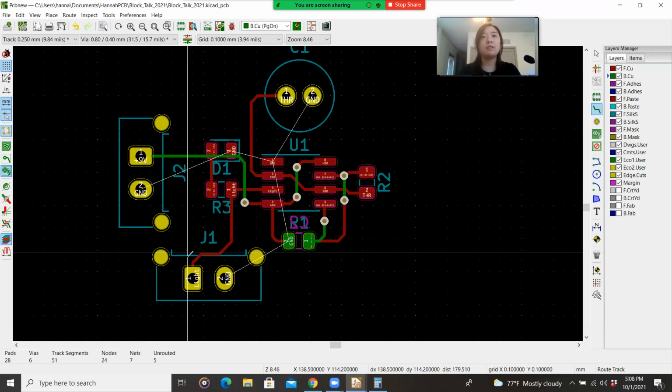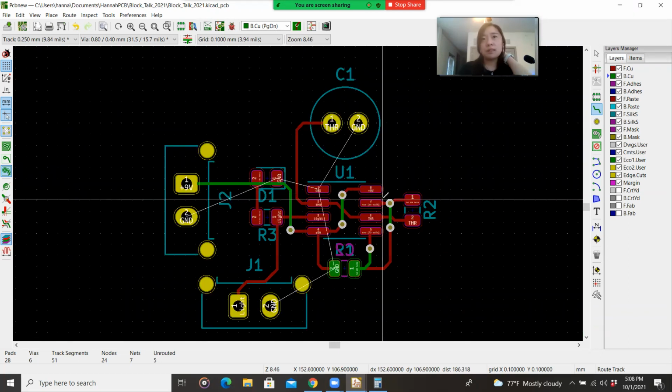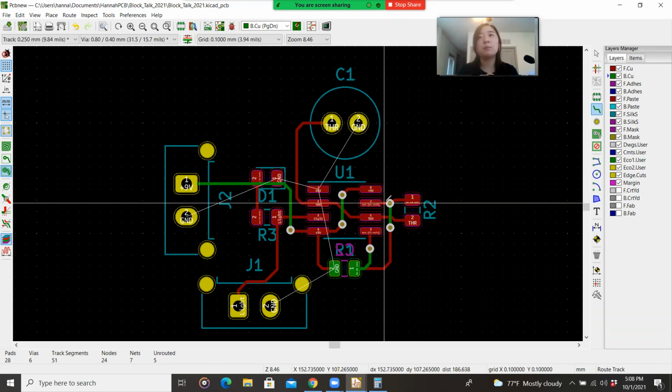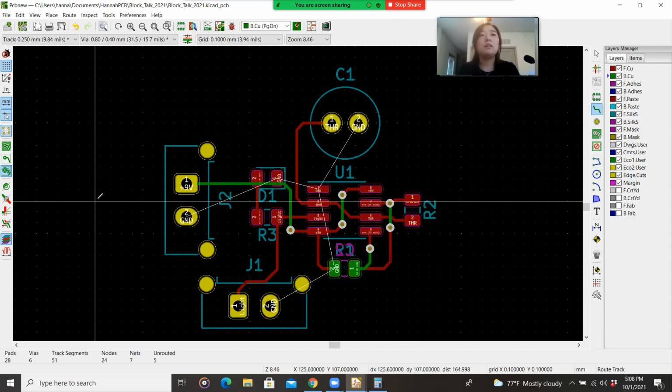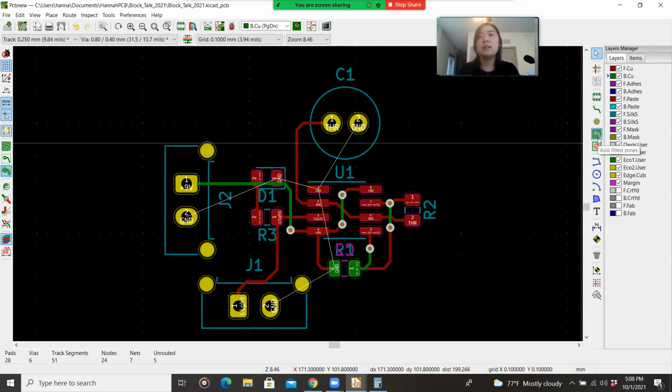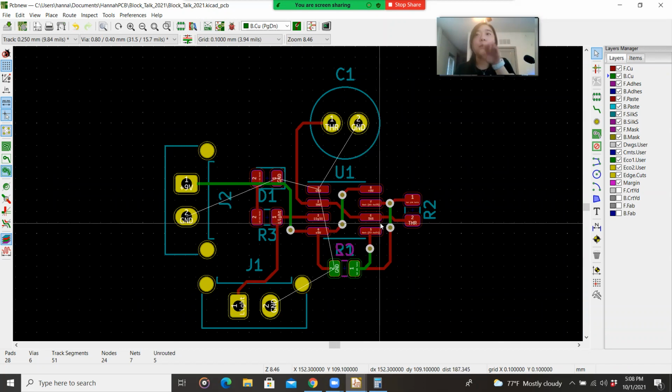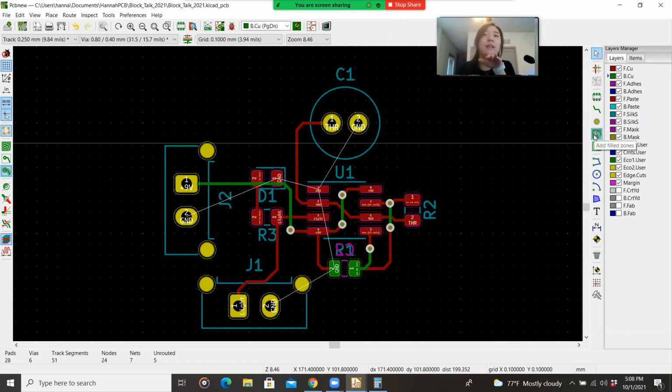So now we have a lot of it laid out. Why was I holding off on these ground planes or ground connections? Well, one useful thing to do is to lay out something called a fill zone or a copper pour, where that entire copper layer besides the traces is going to be a certain voltage level or signal, and we often label that ground. And why do we choose ground? Well, it helps reduce noise, one, and it ensures that each of these paths has a really short path to ground. They can fairly easily all connect to ground.